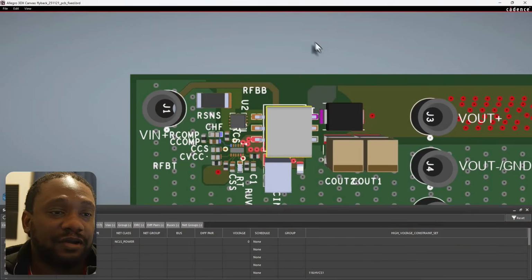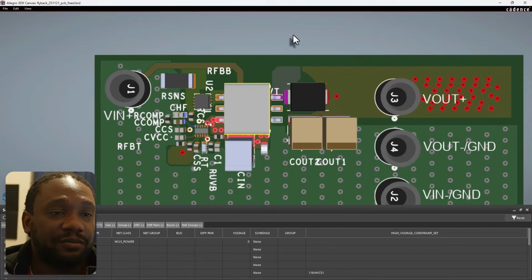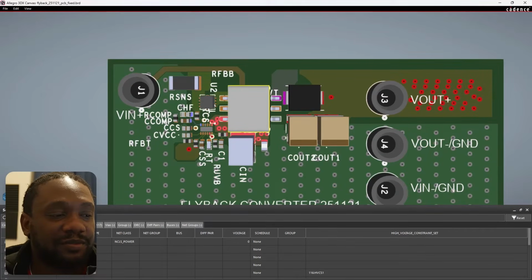If you provide a continuous return plane underneath wherever that current is going, so your current trace is on the top and a continuous return underneath that layer, and then you stitch that return near the edges of your PCB, the field coming off those traces is going to collapse very quickly, and all that ringing that you'll get in your circuit tends to die off. So let's visualize that. Right, so we've got the PCB, and let's take a look at some of these nets.